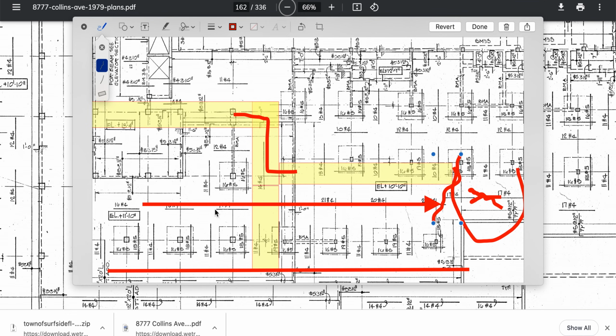That's part of my butterfly failure right down the middle here, because this is all tributary. This is all tributary, right from here to here, no matter what anybody tells you. And there's the loading of the concrete and the steel of the planters here, and then we have the loading of the cars over here. So we get the extra loading across our zones.